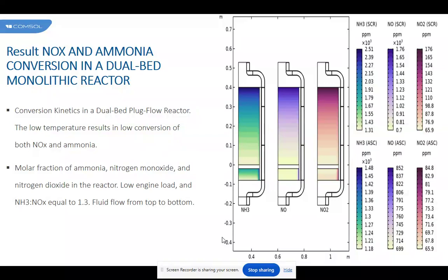The temperature differences along the reactor axis, at the center of the reactor and at the edge of the beds, are seen here in this simulation. Close to the inlet of the first bed, the temperature increases both at the center and along the SCR edge. This is due to the exothermic reactions. After the first rapid temperature increase, the increase in the temperature is slower, and at the edge of the first bed, the temperature instead decreases due to the heat flux to the surroundings.